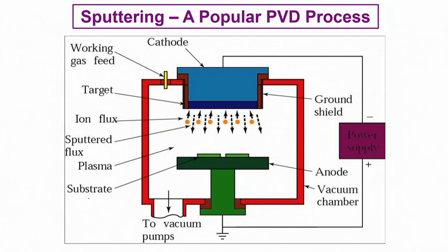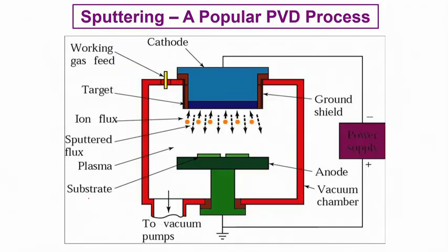Now, sputtering is, in simple words, a process where you scoop the material from the surface, literally atom by atom, by way of shooting certain tiny little projectiles, and in the process those scooped out species or atoms, neutrals, will find their way to deposit onto a colder substrate, and that's the process of sputtering. So let's try and explain what exactly it is.